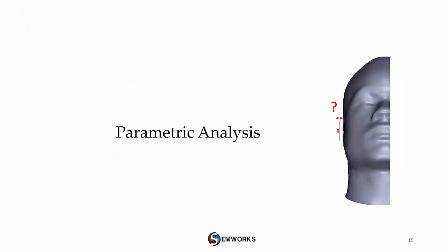We move now to the final part, which is using a parametric analysis with varying the distance between the studied antenna and the human head, in which SolidWorks allows the variation of the geometrical distance with HFWorks simulation results in a single parametric study and in a single project. Let's check the HFWorks interface and the setting of the design scenarios.